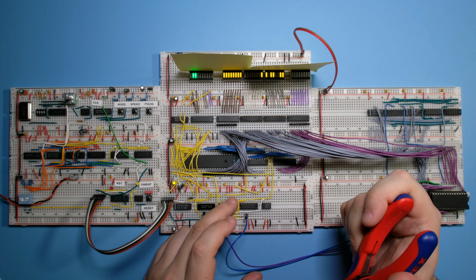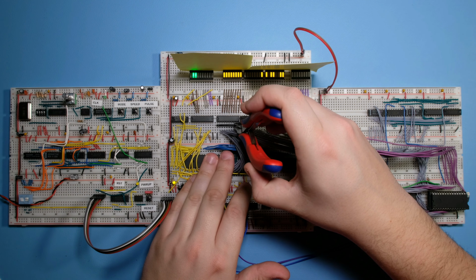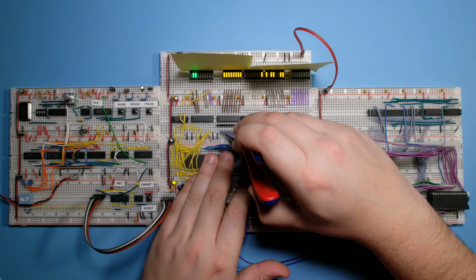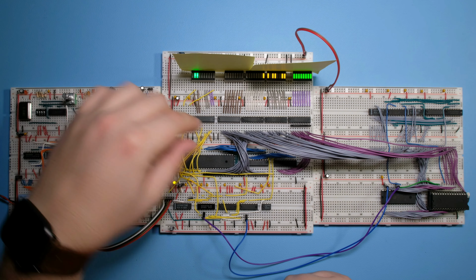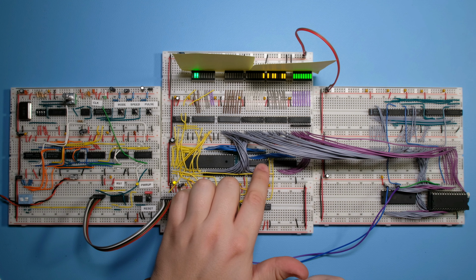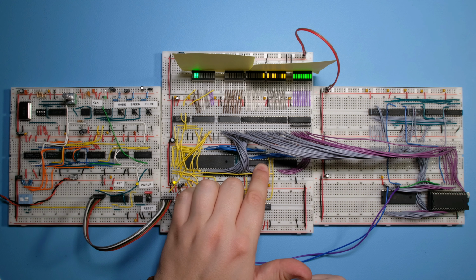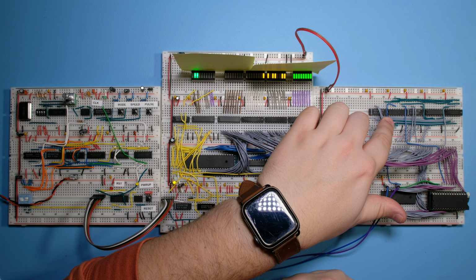And then we need to pull down the output value. Oh, sorry, we need to pull up the output value. Let me do that here. There we go. The reason I disabled this chip is because it's an HCT version and I think it's not fast enough, but I don't have an AC version in stock, so we'll have to wait for that. So I disable the bank address so that the HCT30 here returns the correct signal.